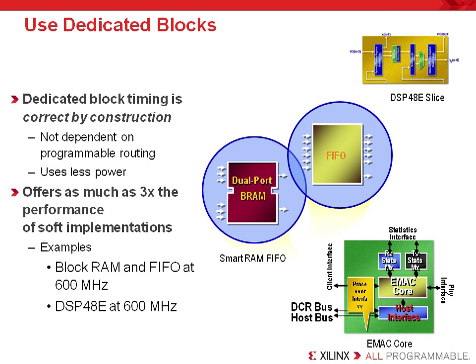This slide is trying to highlight some of the benefits of the dedicated hardware resources that exist in the newest FPGAs. The most useful of the dedicated hardware resources is the DSP slice and the block RAM resources. Besides using less power and saving primary FPGA resources, that is, LUTs and registers, using the dedicated resources makes it easier to estimate timing. This is because the architectural delays of the dedicated resources are known before place and route.